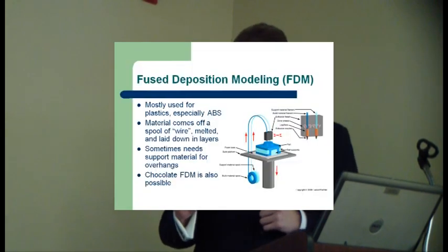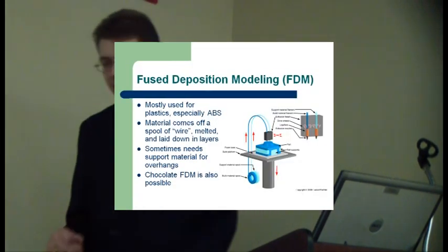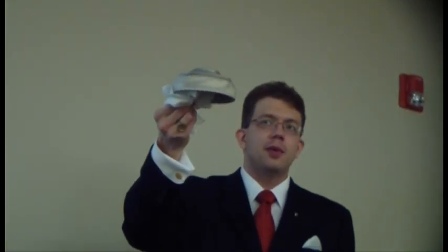You can also use an FDM model, let's say here, for sand casting. In this case, I have a sample here. There's a company called MagnaFlood in Amityville, and this is an FDM model. I'll explain what that means in just a second. And this was 3D printed out of ABS, I believe. And they use that as a pattern for sand casting, and they make this one out of aluminum. And they make hundreds and hundreds by that method.